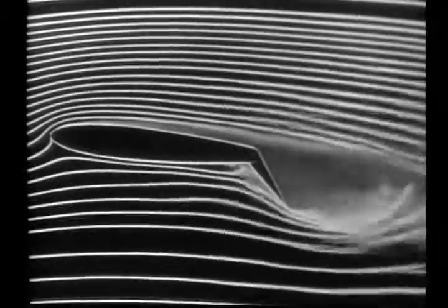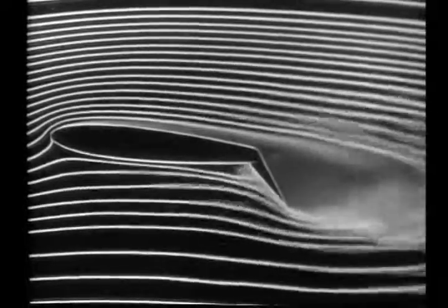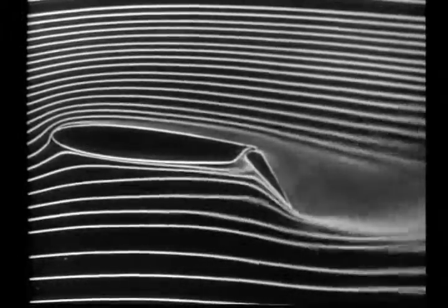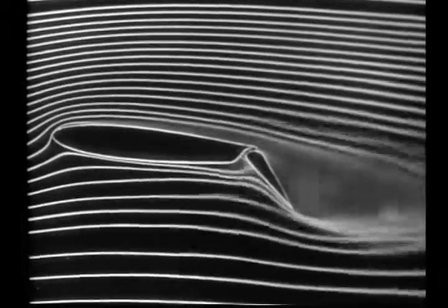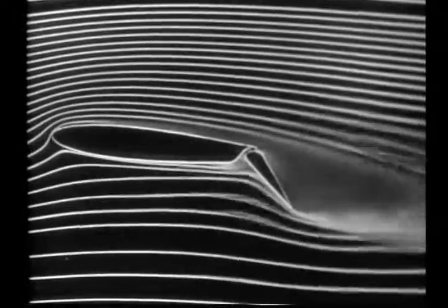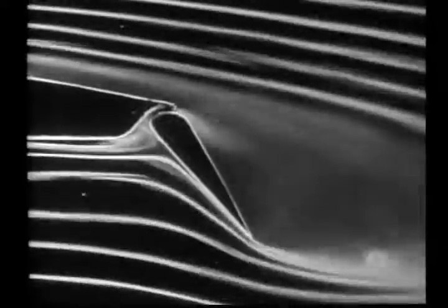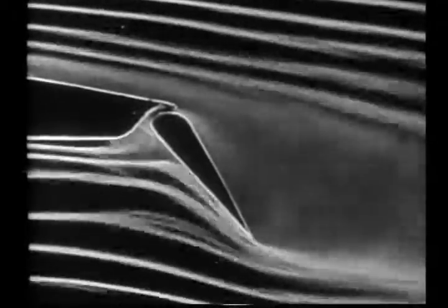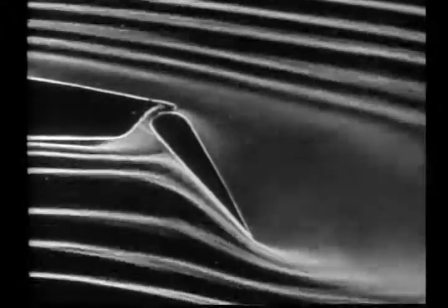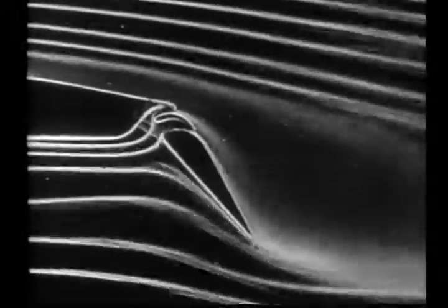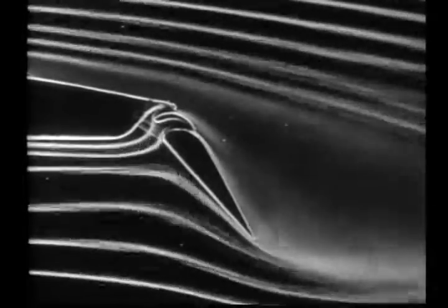This same concept can be used to decrease the extent of separation on a deflected high lift flap. Air can be led from the high pressure region below the flap through a converging channel and ejected over the upper surface close to the point of minimum pressure. This helps to overcome the strong adverse pressure gradients existing on the upper surface of the flap. Multiple slot arrangements, though more complicated, have proven to be particularly effective.